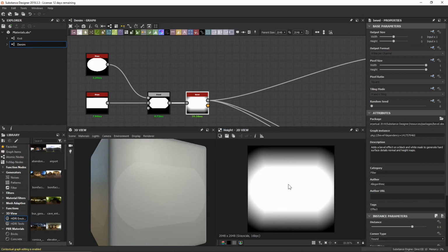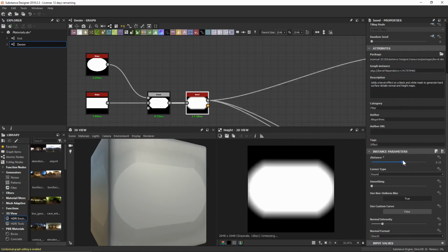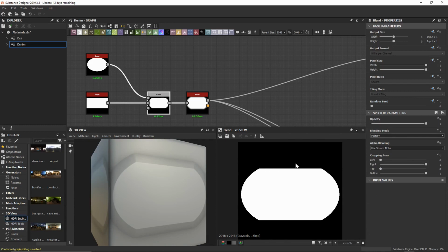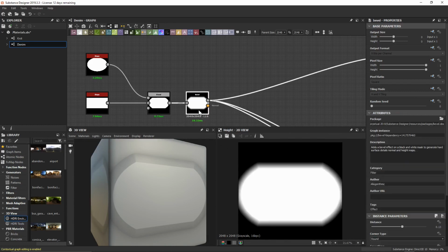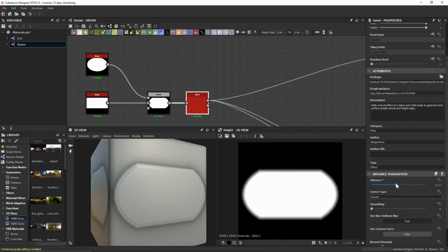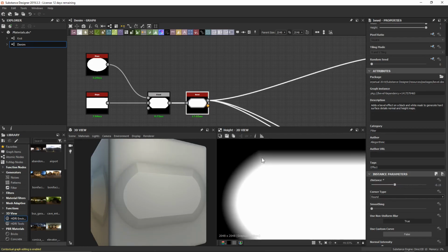It's going to be used to simulate bevel or chamfered edges if you're familiar with 3D at all. So with this distance slider, when it's in the positive, we can see that it's going to extrude a gradient outwards from our initial shape. However, if I bring this slider into the negative, it's going to cast inwards instead and create, again, this kind of beveled edge.